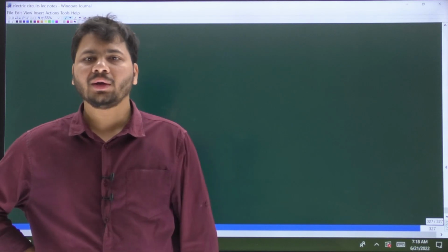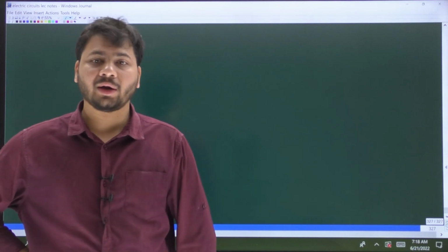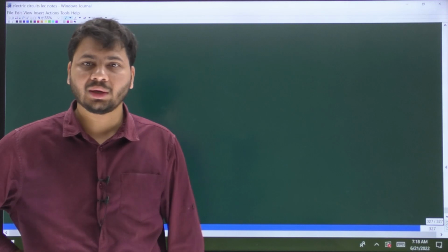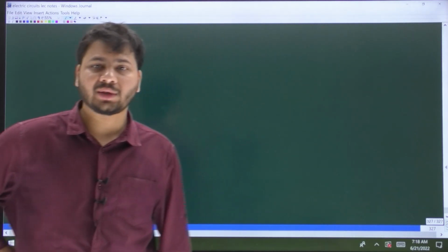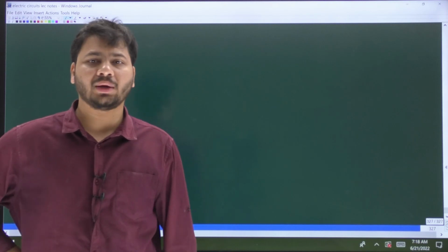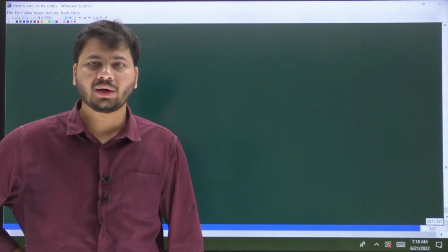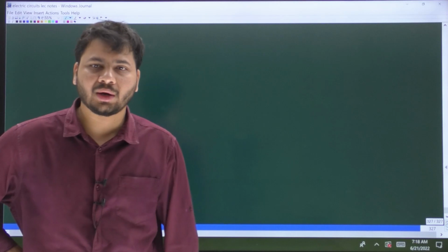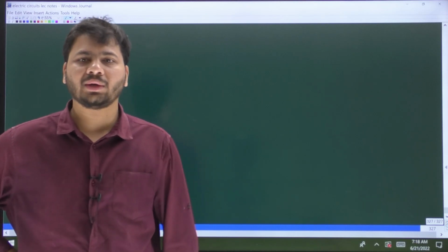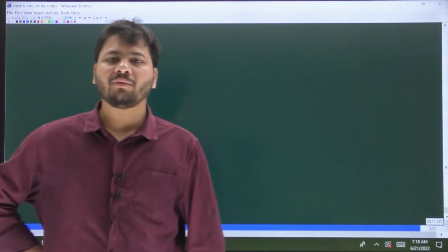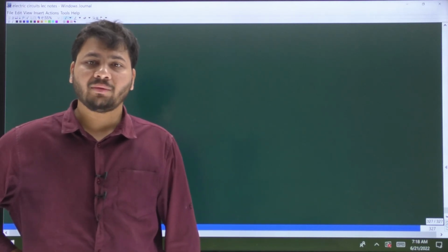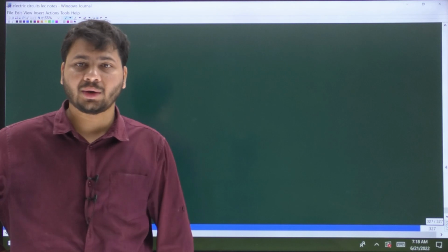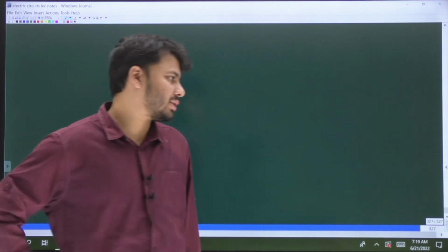So what will get modified? It's only the amplitude and the phase angle that will get modified, but not the frequency. And this is true as long as the circuit is linear. Because at sinusoidal steady state, every voltage and every current is sinusoidal, we have a new notation to represent these sinusoidal functions of time. It is called the phasor notation, wherein every sinusoidal voltage and every sinusoidal current will be represented as a complex number.